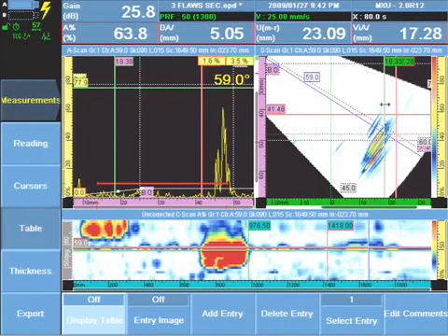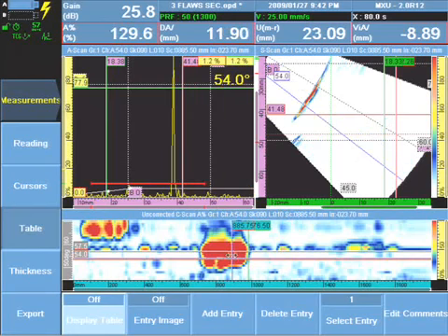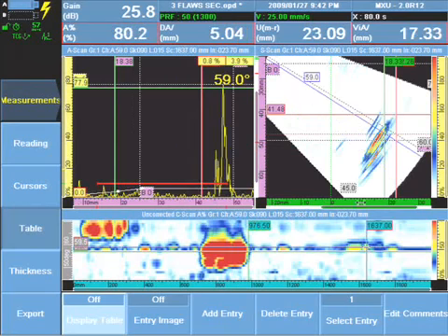Notice the difference between the signal in the S scan and the A scan of cap geometry, of a linear indication such as sidewall lack of fusion, and of an indication of a crack. All the tips and facets of the crack are generating small tip diffracted signals.